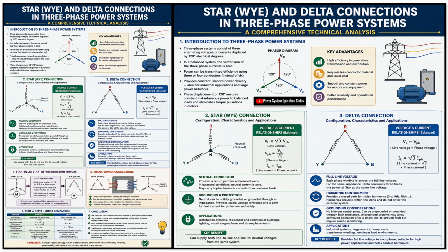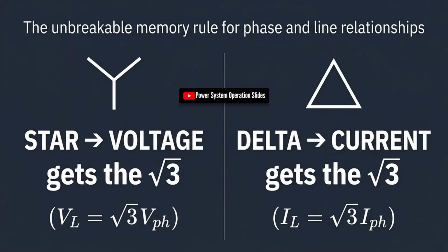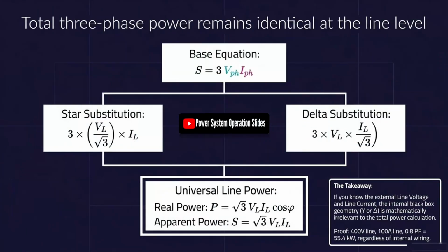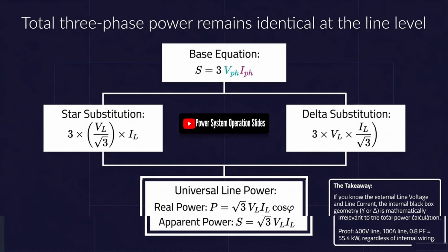Other grounding arrangements include resistance-grounded star systems and ungrounded systems. Resistance grounding limits the magnitude of ground fault current and can reduce equipment damage, while ungrounded systems may allow continued operation following an initial ground fault but can result in increased voltage stress on the unfaulted phases. The grounding method must therefore be selected according to system voltage, equipment characteristics, fault levels, protection requirements, and operational objectives.